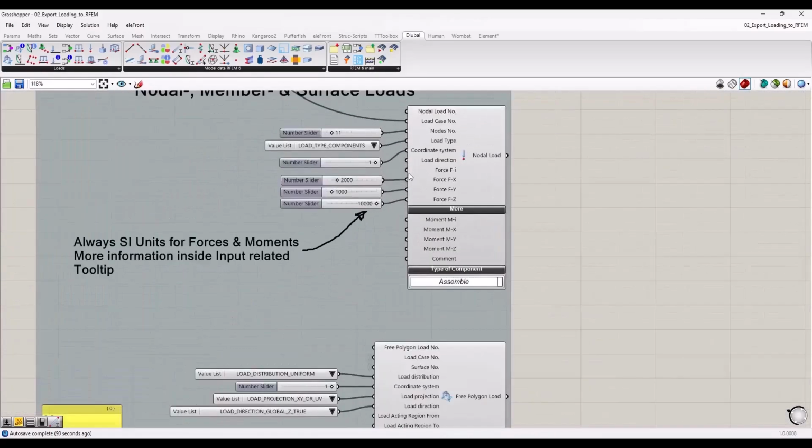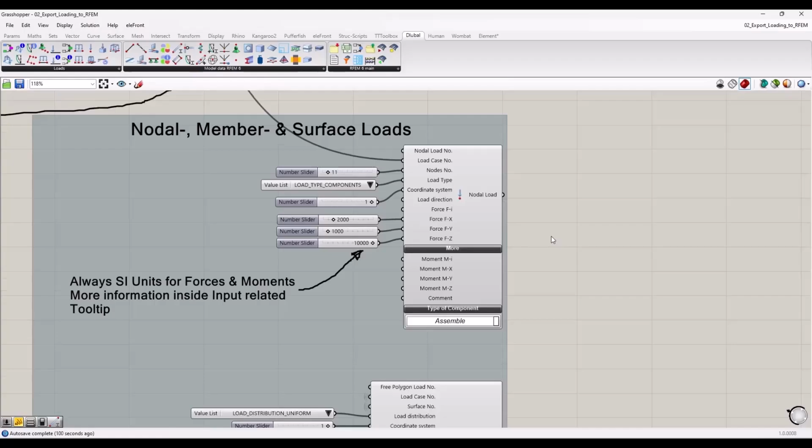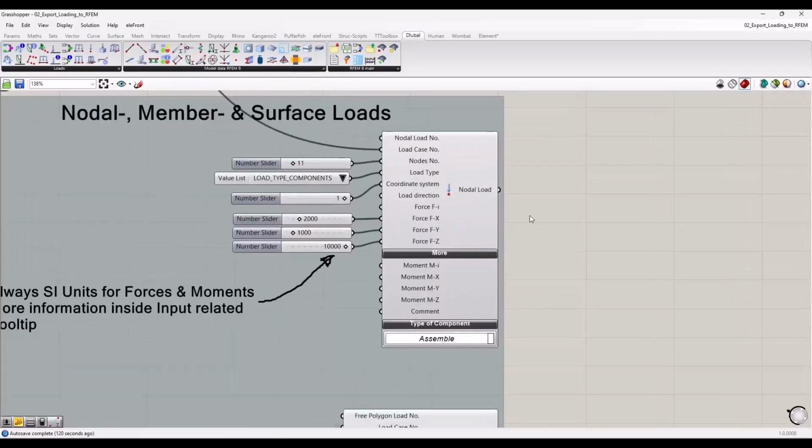I fill these load cases with loads, as I showed before. Here, maybe as a comment, any value that you have to input into our components is usually related to SI units. So meters, Newton, as a simple example, most common stuff. You cannot change these units into anything else. This transformation can be done via a little recalculation if required.